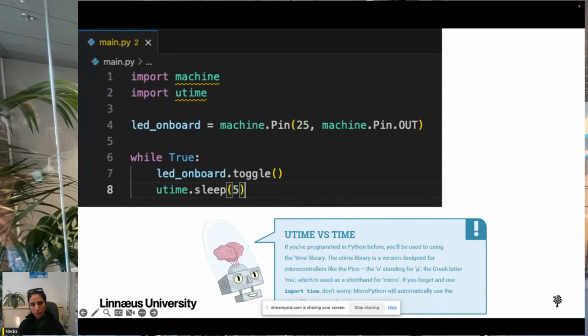When we use Pin.OUT in our code, we are telling the microcontroller to configure that particular pin as an output pin. After setting the pin to output mode, we can then use pin.value to set the voltage level on that pin to either high, 3.3 volt, or low, 0 volt. So that is why we need to set the pin as out.